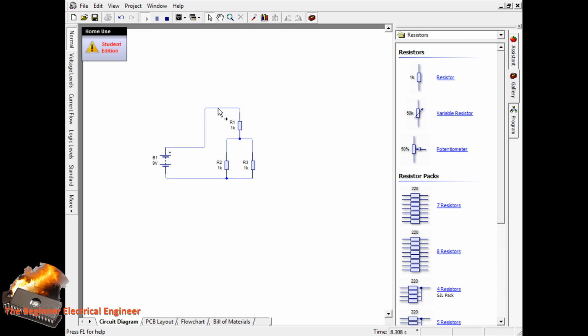As you can see, there is 6 milliamps of current flowing through the entire circuit from the positive terminal, and the resistor is also allowing 6 milliamps of current to flow, but through each side is 3 milliamps between each parallel resistor here. And that essentially means that the sum of each branch of the circuit has to equal the total current in this circuit.